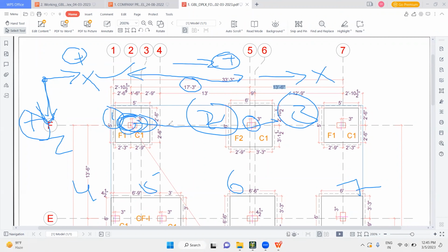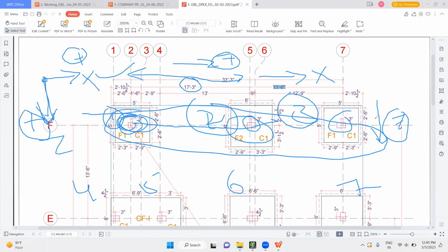When you are selecting these three, 1, 2, 3, and pasting in this direction, it is the z direction, positive. But if you take all these columns and paste in this direction, it is again z, but opposite to the z direction, so you have to indicate a minus sign with the number. For example, when you are copying and pasting at a distance of 10 feet, you always have to mention minus 10 feet. This is the z direction, but opposite to the z direction, so it is minus 10 feet.